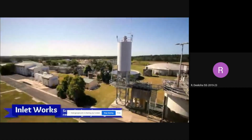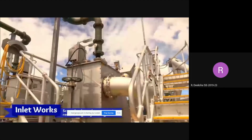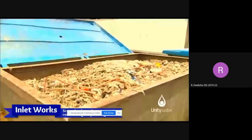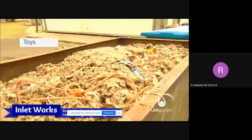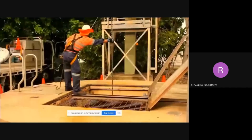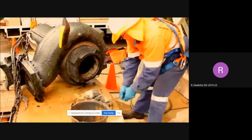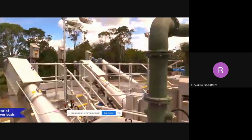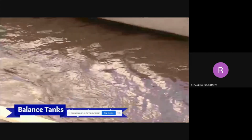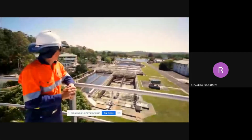When the sewage arrives at the treatment plant, we screen it to remove all the unwanted objects. We find all sorts of strange things that shouldn't be there. Toys, false teeth, jewellery and even underpads. We also find lots of other items that cause big problems for the treatment plant. Things like baby wipes and cleaning wipes, nappies and fats and oils. Once all the sewage is screened, some treatment plants have special tanks that hold all these screened sewage and control how much sewage enters the treatment plant at any one time. This helps to ensure the quality of the treatment is always consistent.